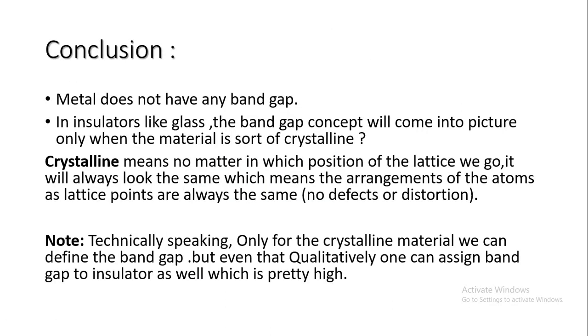Now if somebody asks, can we define the band gap of an insulator? Many people define it. In many books you will also find those materials whose band gap is so large that we can say that is an insulator. Quantitatively, some information is given in each book, but let me tell you the fact that in an insulator like glass, the band gap concept will come into the picture only when the material is crystalline. If the material is not crystalline, you cannot define the band gap, guys.